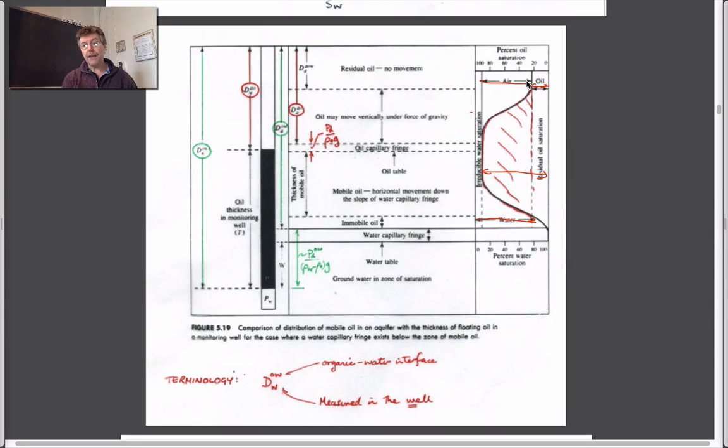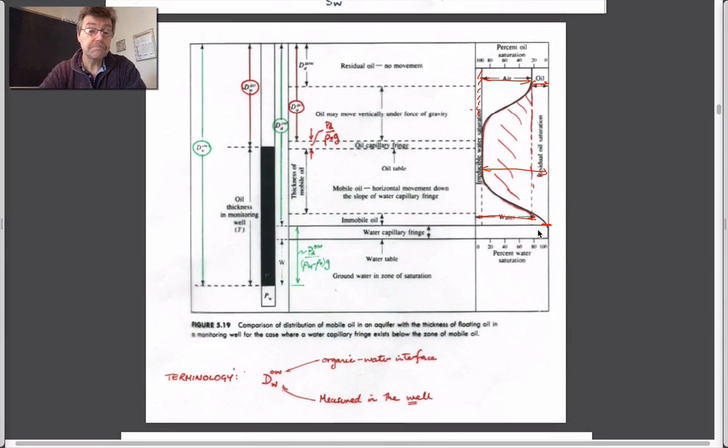This would be the air that's present within the chimney, and maybe water that's saturating at irreducible saturation above, in the vadose zone. And below the water table, it would be almost 100% water saturated, with some incursion of the NAPL, but that dies off because it can't physically push down because it's buoyant, and therefore can't get that far down.